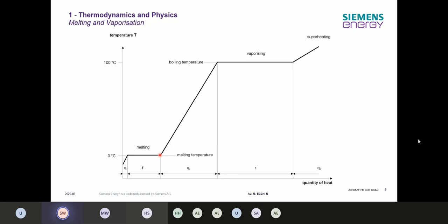And this is something which is not happening, or hopefully not happening, in our power plants. Because as soon as you have freezing somewhere in the power plant, let's imagine your power plant in winter, let's say in Germany, you're getting minus 10 degrees ambient temperatures and you have some pipes outside where water is standing in and they start freezing, then you have big problems in the power plant.